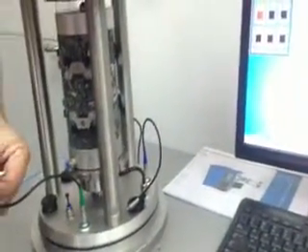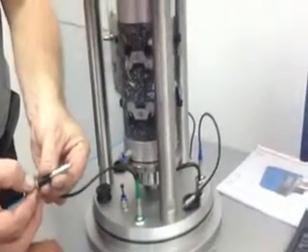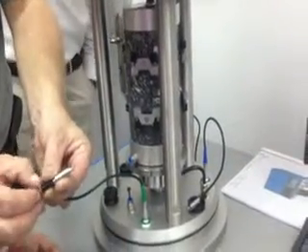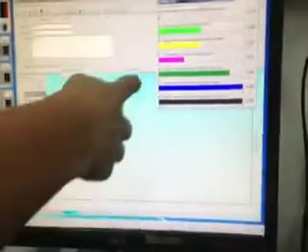So at the moment we put the transducer in, but it's showing full range. So we need to adjust this height here. So we loosen the gold one, and we can adjust this up a little bit. Then we can lock, and we can put back in. See now the transducer. Yep. But it should be the 0.